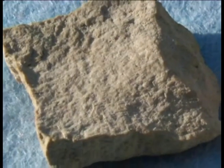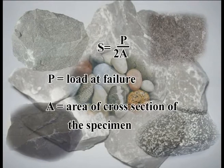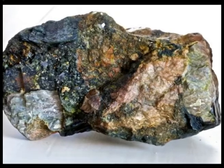It is obtained by using this relation S is equal to P divided by 2A, where P is the load at failure, A is the area of cross section of the specimen. It has been observed that shear strength of most common building stones lies between 70 to 140 kilograms per centimeter square. Tensile strength. It may be determined directly or indirectly.